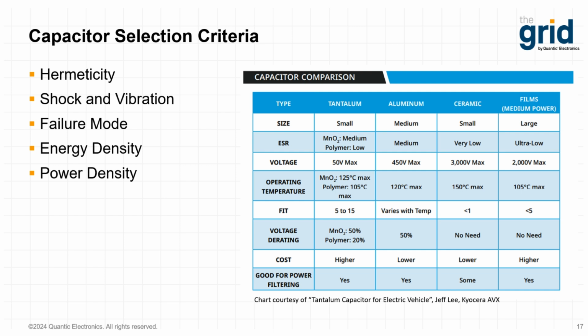So as designers, we must account for the worst case scenario in these low temperature environments as a part of the selection criteria. There are some capacitors, such as the multi-layer polymer film capacitors, as Zach has discussed earlier, that have very stable performance across temperature. And of course, this is based on the unique properties of the materials used to make these types of capacitors. At some extreme temperatures, a capacitor can still work, but we must derate the voltage accordingly.